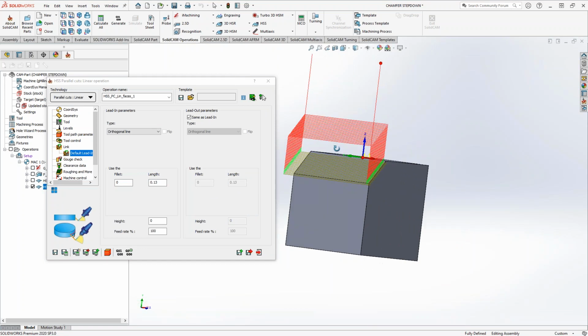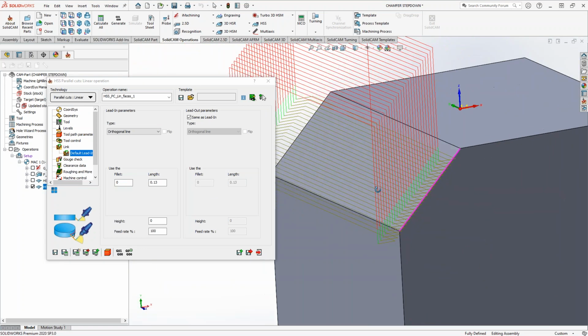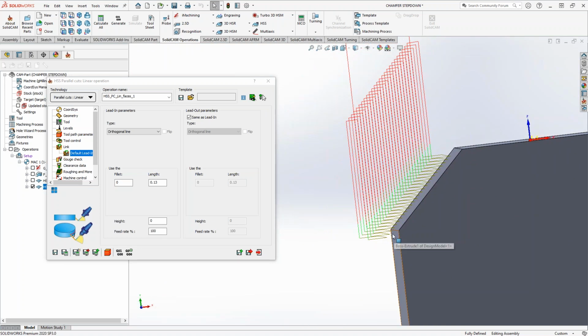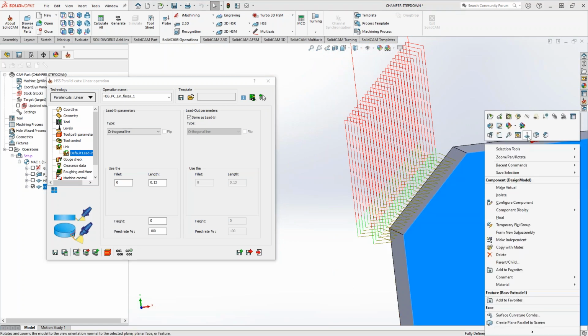So there we go. One-way cut, a little bit of a lead off on the sides there, and a 20 thou step over. And it goes a little past the bottom of the surface there, only because, again, it's trying to keep that tangent point with the cutting surface.